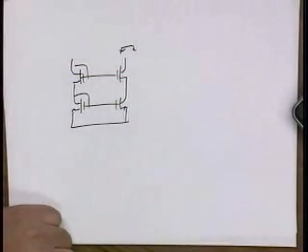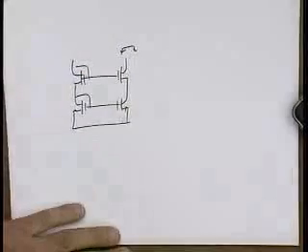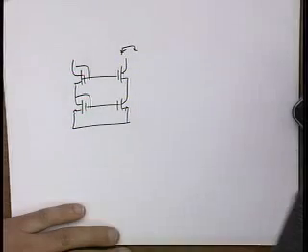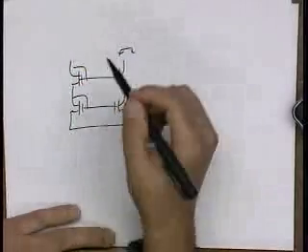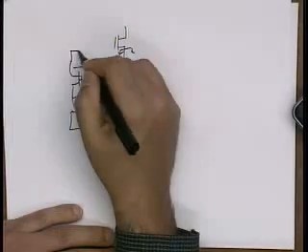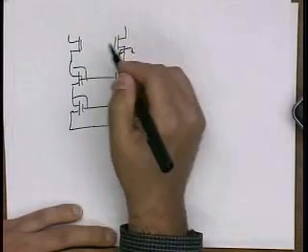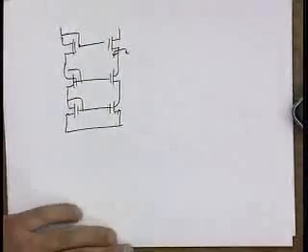Let's say I want even higher output impedance. What can I do? Don't look at the slide. Besides what's on the slide, what else could you do? Stack more, yeah, why not? In MOS devices, you can just keep stacking. It doesn't hurt. There's no base current like bipolar, and so the impedance just keeps going up.